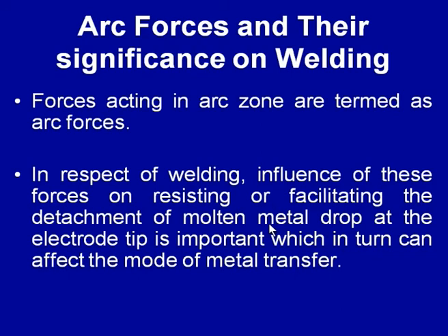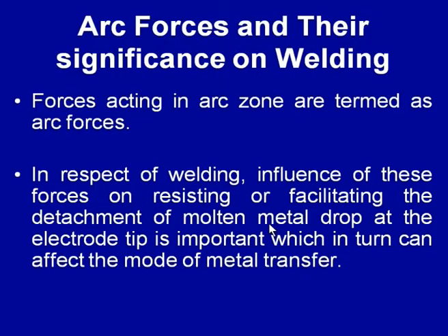This is mainly important in case of the consumable arc welding process, because it directly dictates the mode of metal transfer, that is, how a molten metal drop is transferred from the electrode tip towards the workpiece. Depending upon the type of the arc forces and their magnitudes, the metal transfer is affected.